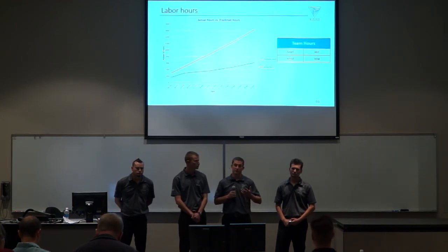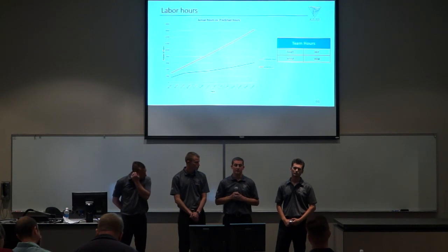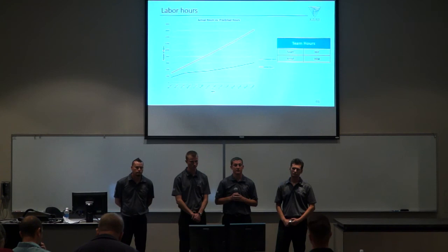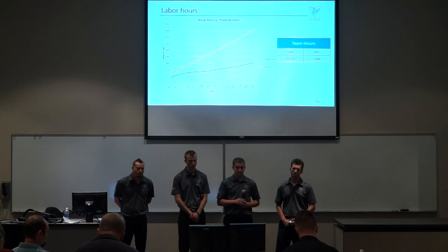Some of the noise in the pressure, some of that's attributed to the dynamic range of the pressure transducers. They were actually 100 PSI pressure transducers. We were looking to measure within 0 to 30 PSI. Yeah, that makes sense. No worries. I was just kind of curious if you guys had thought about that at all.